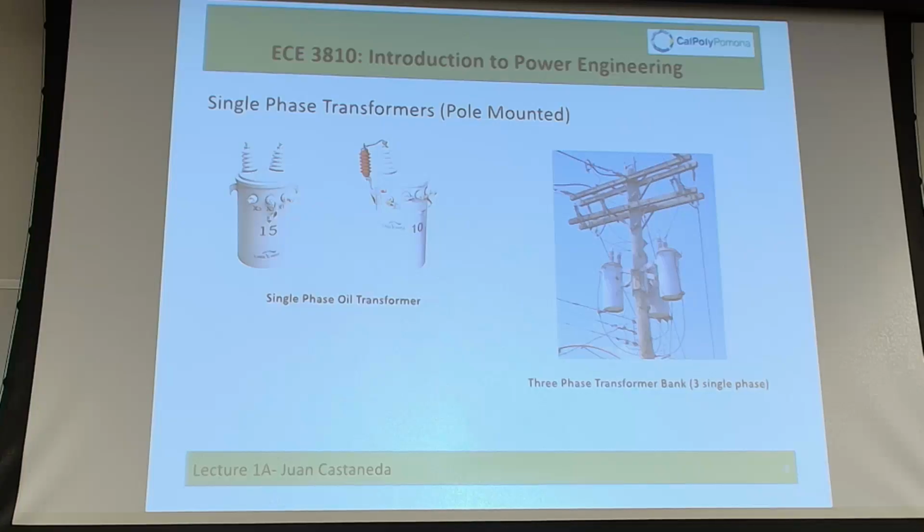There's a lot of reasons, but one of the main reasons is that you want to prevent current from leaking into the insulator. So when water comes, if it's like this, it's much easier for water to go this way, especially when the insulators are really small. What you don't want is this. If I have the insulators like this, I'm exaggerating, but the water can go like this. That drips.